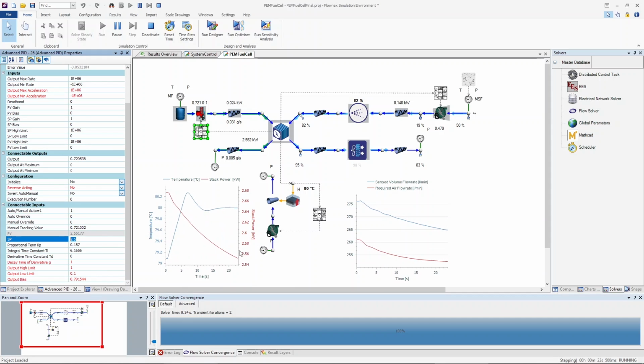So essentially what will happen is when we specify 2.5 kilowatts, the fuel cell stack calculates the required hydrogen as well as airflow rate, and this will then control this valve as well as this compressor here on the right hand side to get the required flow rates, so that you do not have too little or too much hydrogen compared to your oxygen on the air side.